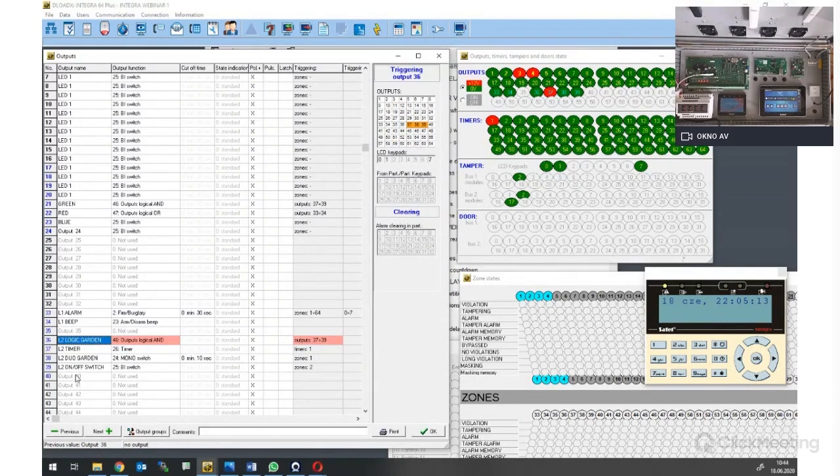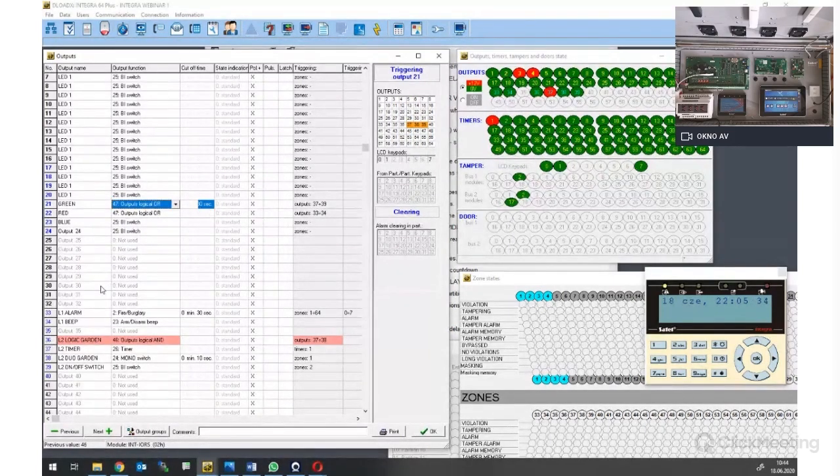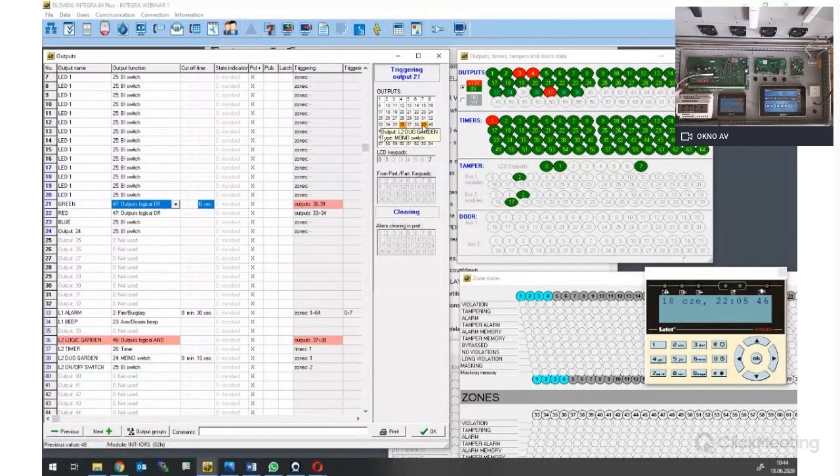And then I will disable one thing, because right now I don't want to have the master switch. I want to have this turn the light on and off, but on the physical output I will use OR, because I'm using the same OR logic with the timer and the detector, or the switch to turn off the light. And in here I just marked 36, I will turn it off, and 39, because this will be my logic and this will be my switch on the wall. And if I program everything properly,